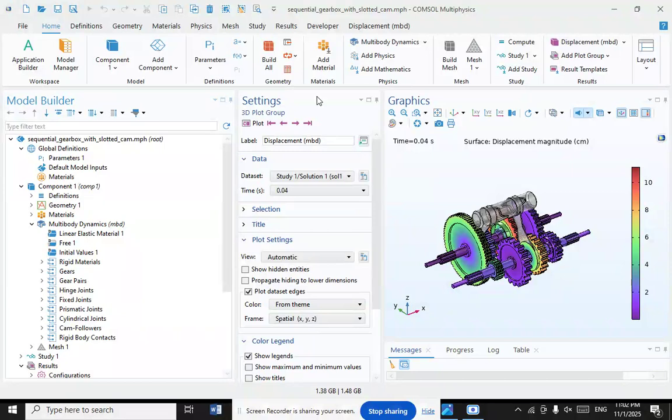Common metals for synchronizer rings are brass and steel, and are produced either by forging or sheet metal shaping. The latter involves stamping the piece out of a sheet metal strip and then machining to obtain the exact shape required. The rings are sometimes coated with anti-wear linings, also called friction linings, made from molybdenum, iron, bronze, or carbon, with the latter usually reserved for high performance transmissions due to their high cost.